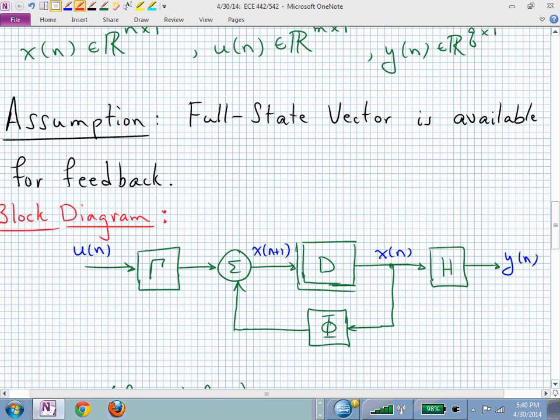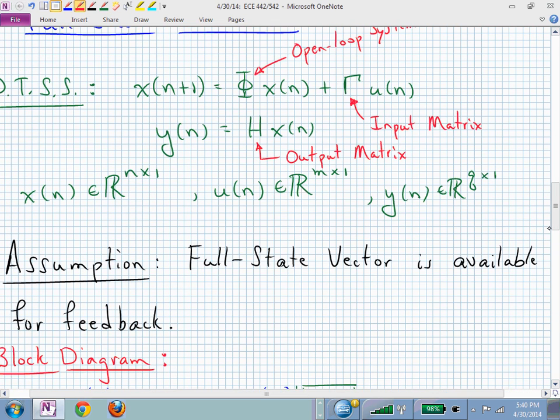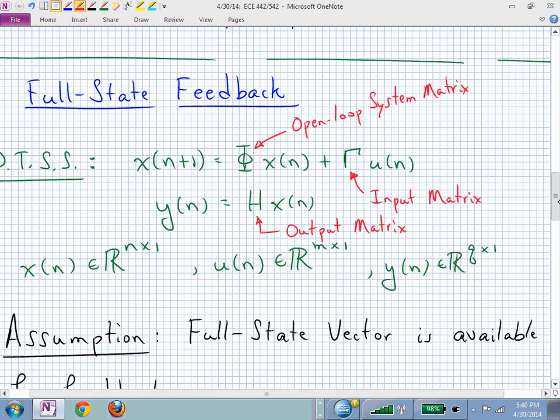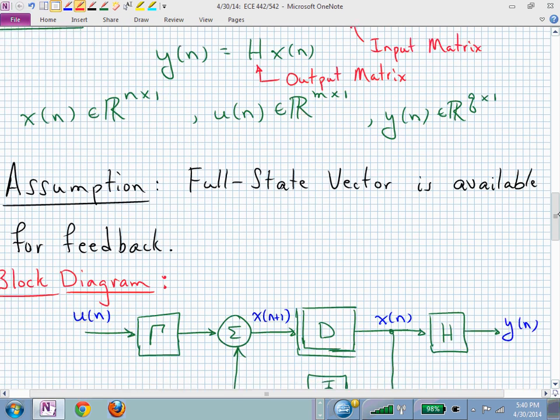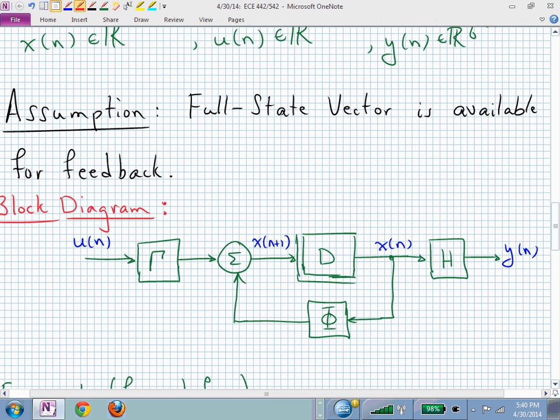We create our output signal as a linear combination, h times the state vector. And that's our output equation, y is equal to hx. Is that clear? We can either write it this way, depending on how you like to think about things, or we could write it this way. A lot of times I will not necessarily draw that sort of three-dimensional shadowing D to indicate that we have more delay blocks consistent with the size of our system, phi.